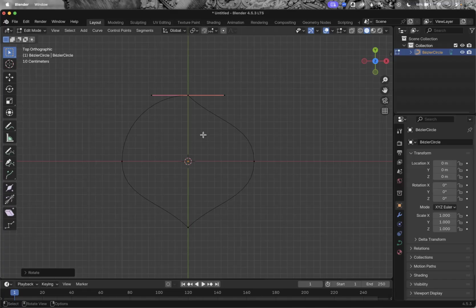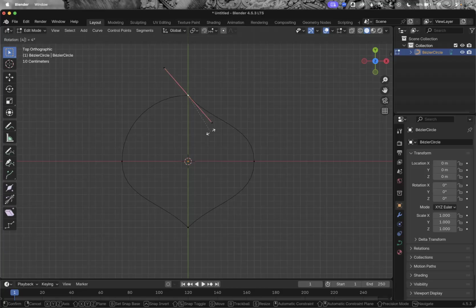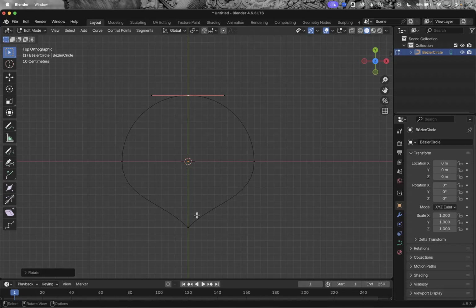That looks good. Now I'm going to click on seemingly the same point, but you can see the handles have moved, which means I got its double. So now I'll press R and 45 again. And you can see this has made it worse, but if I hit the minus key, we're good. So when you're putting in parameters in Blender, you can hit the negative symbol before or after you've put the number in. It doesn't matter.